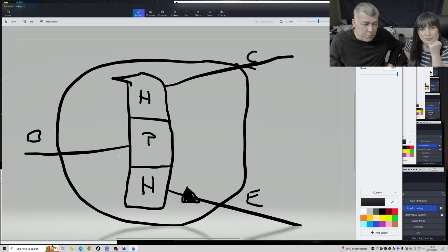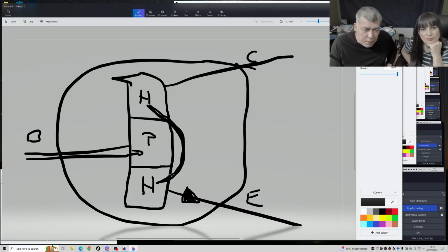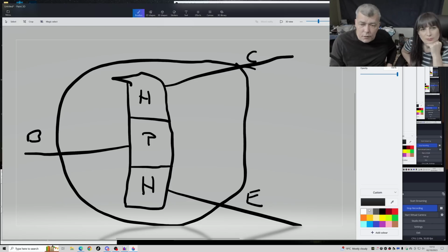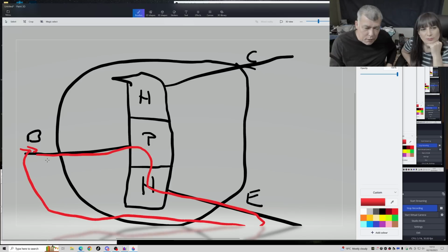Now, like I told you, probably you didn't remember. If you apply current to the base, but current maybe is too complicated a word, so let's say 0.7 volts on a transistor. When you apply voltage to this junction inside the transistor, the other 2 junctions will start driving the power. You understand? So in this case, you will have 2 current flows. As soon as you apply voltage to the base, you'll have a current flow from this junction to this junction, which is getting close to the ground, and you will have your major current flow from the collector to the emitter and out.